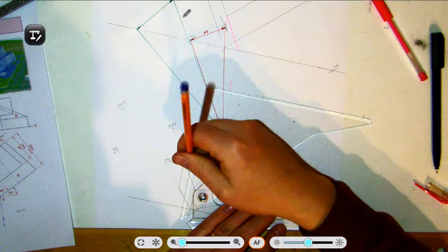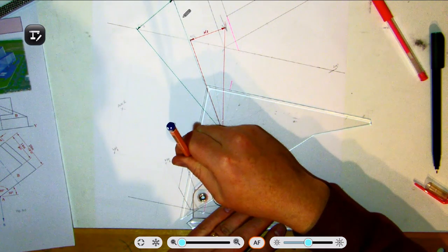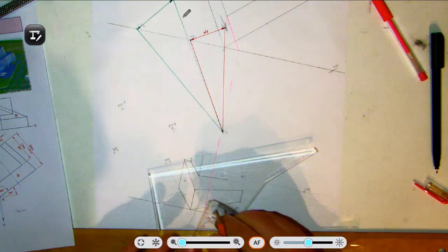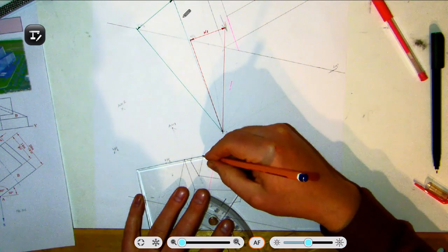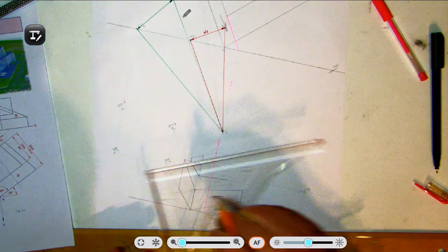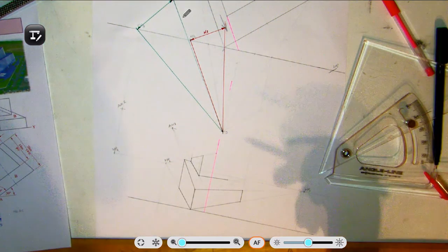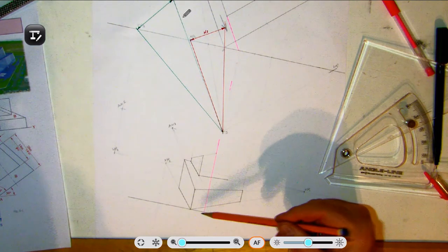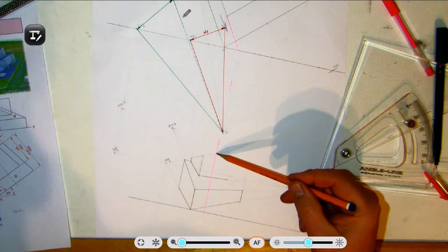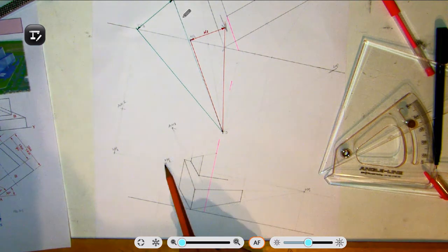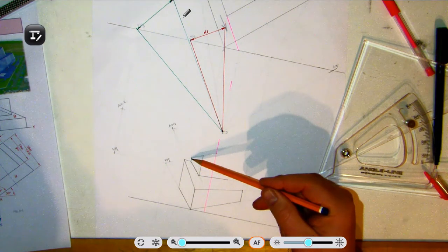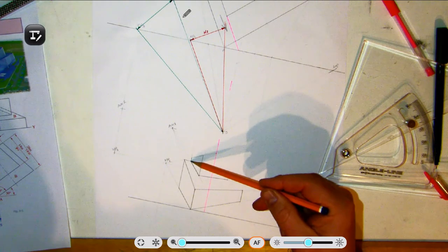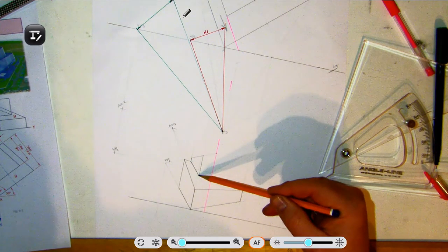and I can draw this edge now in heavy, and dim edges are found by using that height line. So again, just to recap on that height line, this is the height line brought down to plan, mark off 75 high on it, join it back to VP2, and then what this allows us to do is draw this line and also this line at their correct heights.